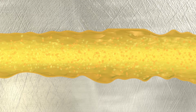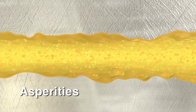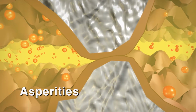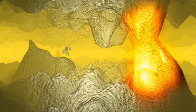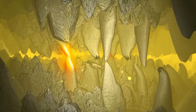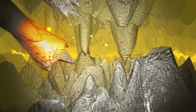The surfaces of all metal parts, no matter how smooth they appear, actually have small peaks and valleys called asperities. Normally, the lubricant forms a boundary between the two metal parts, preventing the asperities from touching one another as the parts move. Without proper lubrication, the asperities come into forceful contact and actually cold weld to one another. As the parts continue to move, the weld breaks. This releases small metal particles that can cause additional damage to the gears and bearings.